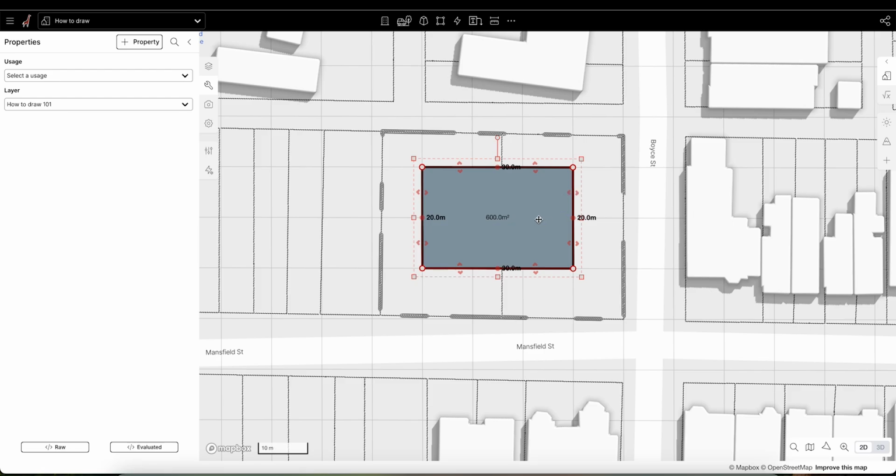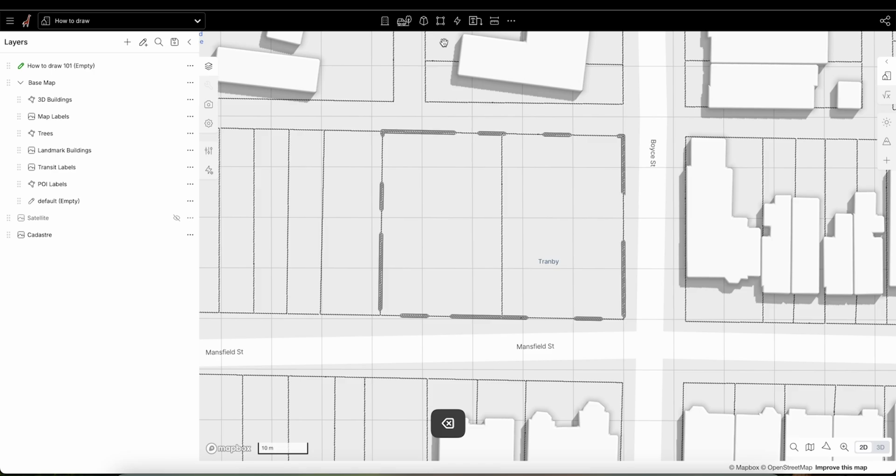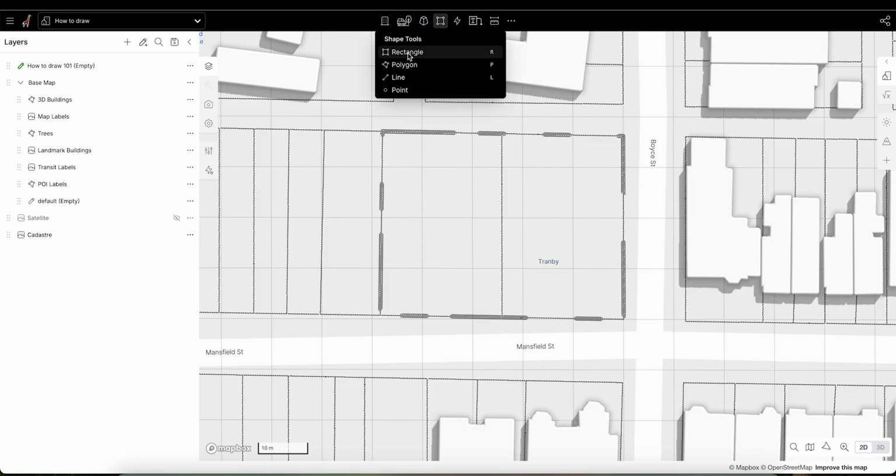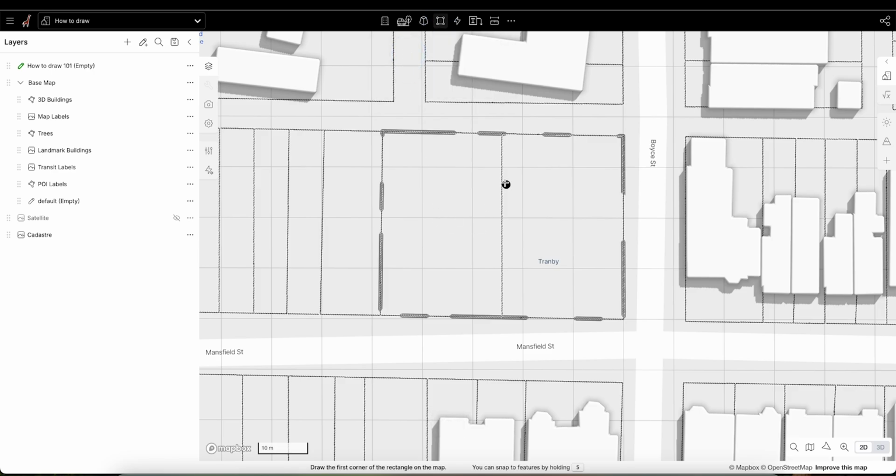You can also define the rectangle just as we did with the grid system by typing in the dimensions. So let's talk through that one as well. Going back up to rectangle, and maybe for this one I won't use the grid to define the rectangle. So I'm currently in a freeform dimension, but I can override that with, say, typing 12 on my keyboard.